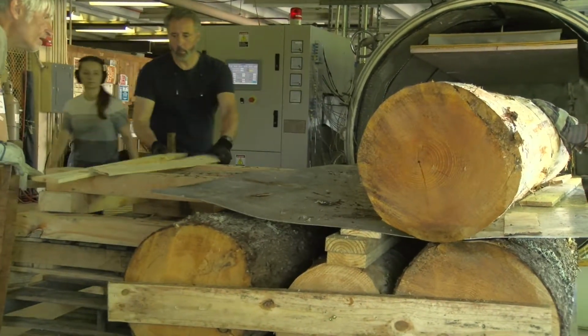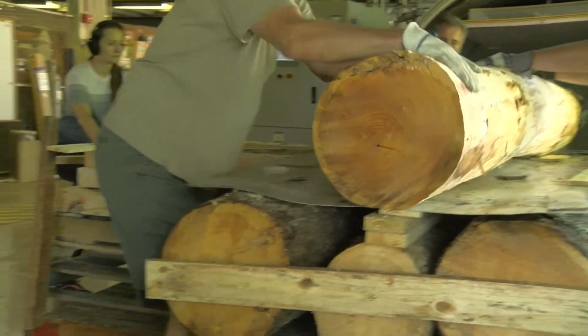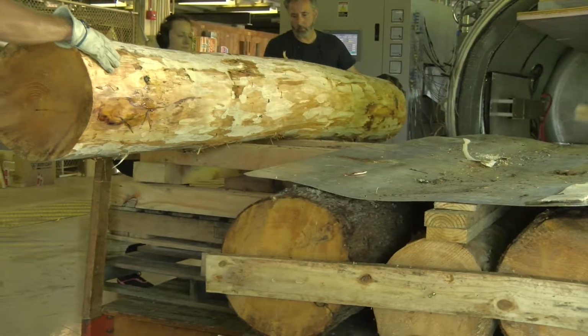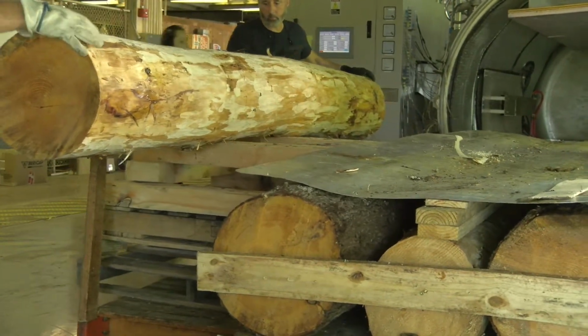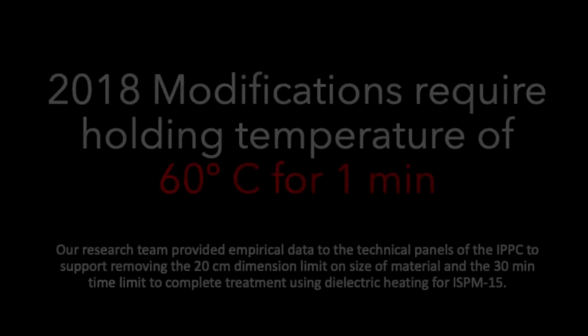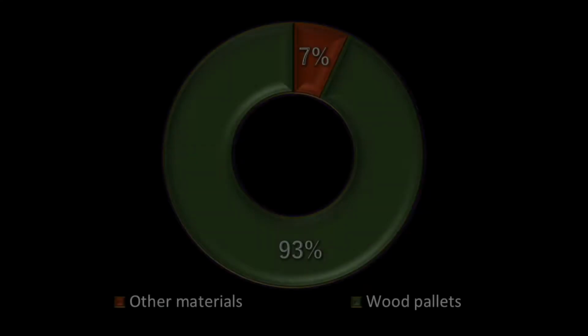6 years after our research team submitted the required efficacy data, dielectric heating for radio frequency and microwave technologies were approved in 2013 as the first new treatments by the Commission on Phytosanitary Measures of the IPPC. And important modifications were made to the standard in 2018. The treatment standard requires holding a temperature of 60 degrees Celsius through the profile of the wood materials for at least 1 minute.